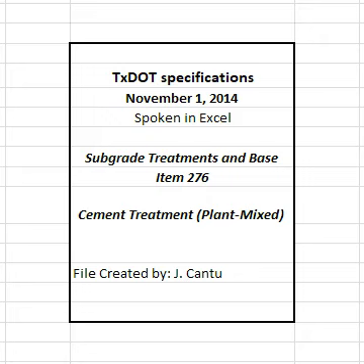4.6 Curing. Cure for at least 3 days by sprinkling in accordance with Item 204, Sprinkling, or by applying an asphalt material at the rate of 0.05 to 0.20 gallons per square yard, as shown on the plans or directed. When a section is microcracked, cure the section for an additional 2 days after microcracking. Maintain the moisture content during curing at no lower than 2 percentage points below optimum. Continue curing until placing another course.